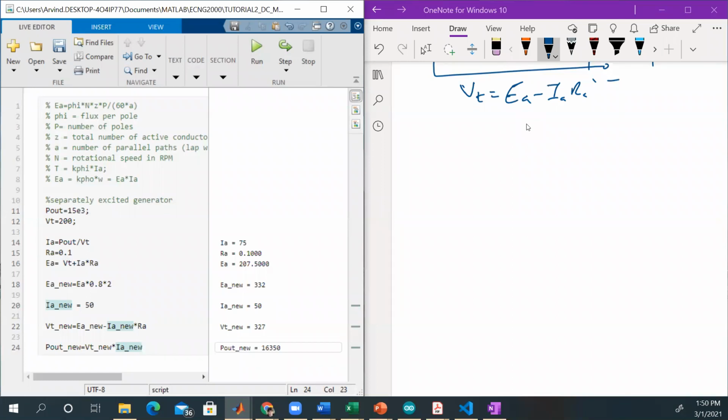So if you use the motor for a higher torque application, you're going to draw more current, your winding is going to heat up. That heat is going to start to damage the insulation. You mightn't see any difference in the motor immediately, but instead of the motor giving you 20 years life, it might give you 15 years life or 10 years life.